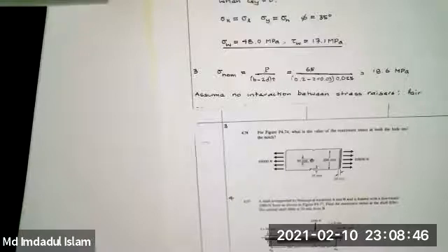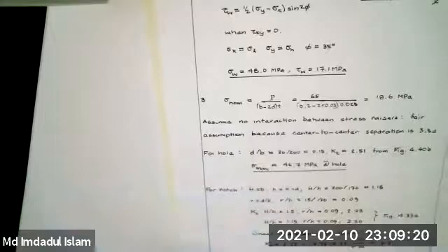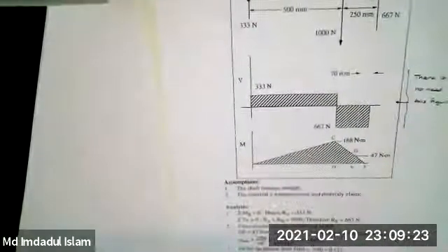It's not precise, and there are some solutions when you have 2 stress concentrators. In practice, you can go look at Peterson stress concentration factors and see the sort of interactions. Obviously, you wouldn't do this in the test. There are 2-hole problems and stuff like that, and you can see how much it does, and you can get a factor from that, which would be a better way of doing it. But if you didn't have access to that, then you could do something along the lines of what you're saying.